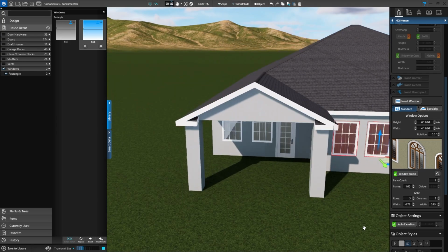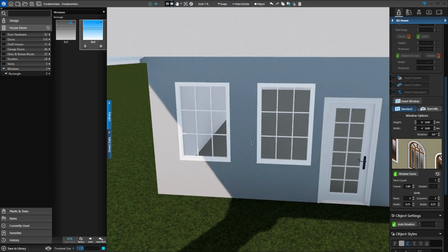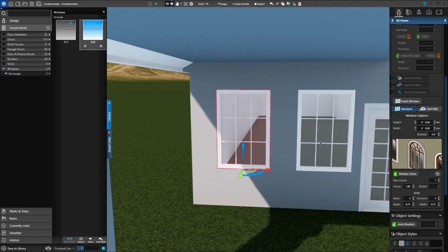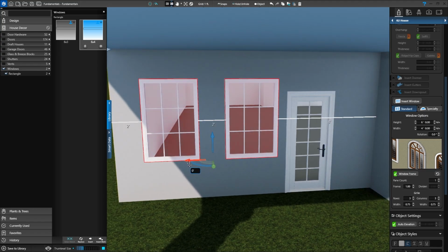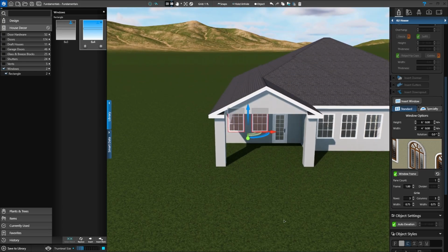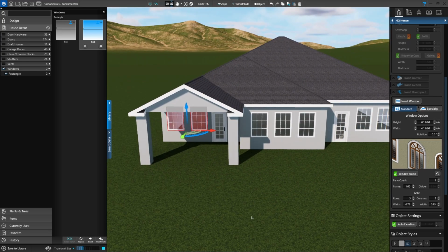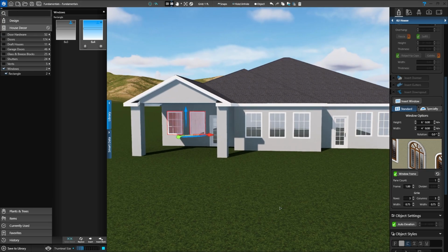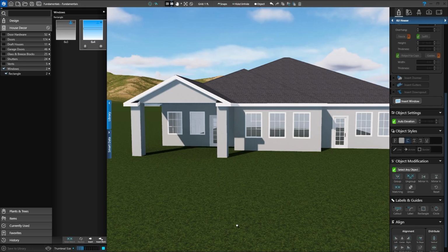And do the same thing with my third wall over here. Just going to check and see what the placement looks like. Maybe move both of these over a little bit, so I hold the Control key down to add additional objects to my selection. And remember, if you have something selected and you want to deselect it, when you're in the 3D environment, go up and click on the circle with the line through it, and that will deselect your shapes.